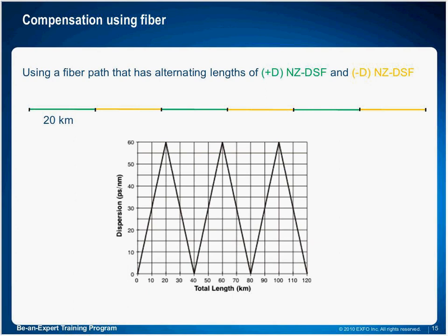So there are several things to take into consideration. What is the network that is currently in place? What is the total length of the fiber that needs to be worked around? And also the knowledge of the receiver equipment. Is it coherent or not? What are its tolerances and things like that? These are elements that need to be taken into consideration.